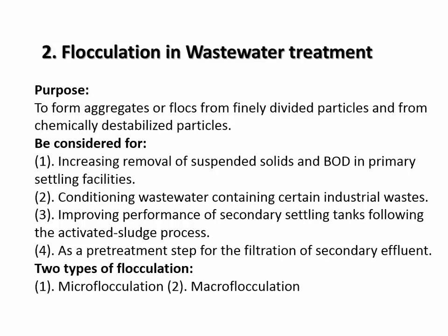For flocculation in wastewater treatment, the purpose is to form aggregates or flocs from finely divided particles and from chemically destabilized particles. It is always considered for increased removal of suspended solids and BOD in primary sedimentation facilities, and conditioning wastewater containing certain industrial wastes, and to improve performance of secondary sedimentation tanks following the activated sludge process, and as a pretreatment step for the filtration of secondary effluent.